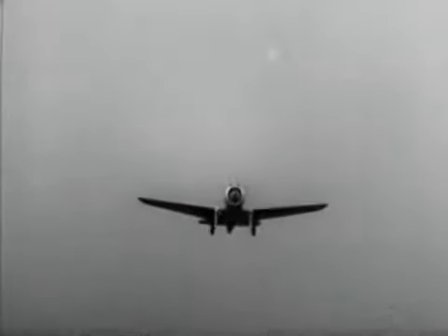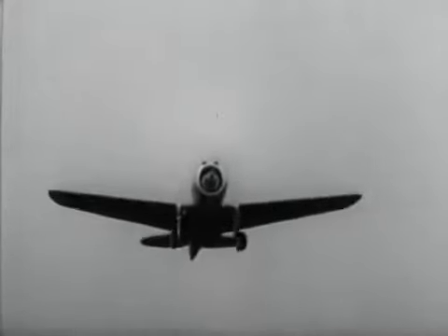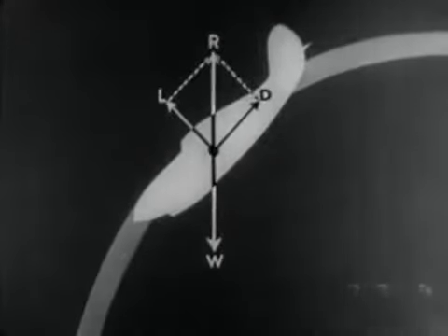Although the angle of attack is constant for any given wind tunnel test, in actual flight, the angle of attack of the airfoil varies with changing attitude and speed of the airplane. Consider the case of an airplane flying horizontally at a small positive angle of attack. As the controls are set to put the airplane into a dive, the angle of attack decreases and the speed